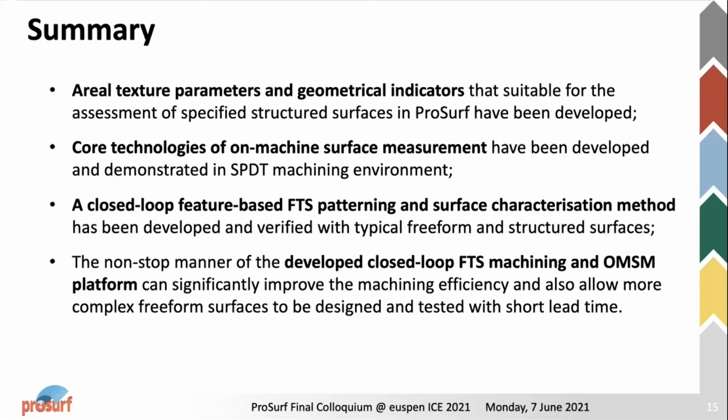A closed-loop feature-based fast-tool-servo patterning and surface calibration method has been developed and verified with typical freeform and structured surfaces. The non-stop manner of the developed closed-loop fast-tool-servo machining and on-machine surface measurement platform can significantly improve the machining efficiency and also allow more complex freeform surfaces to be designed and tested with short lead time.